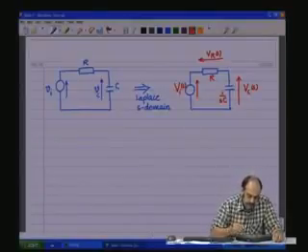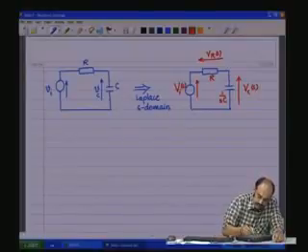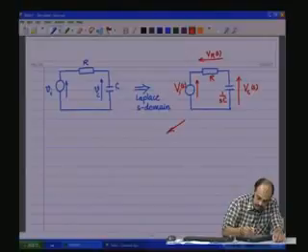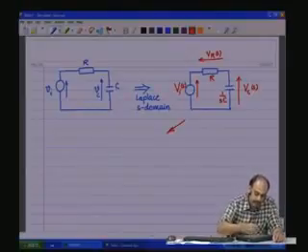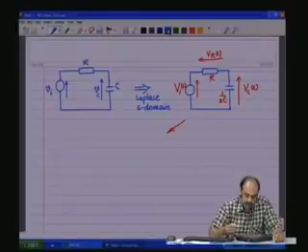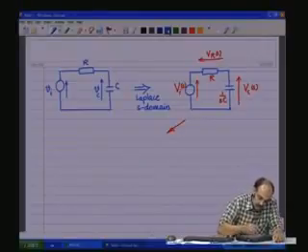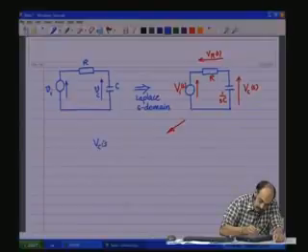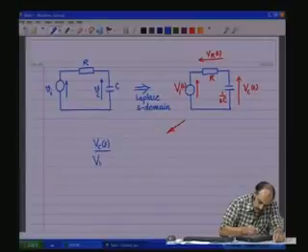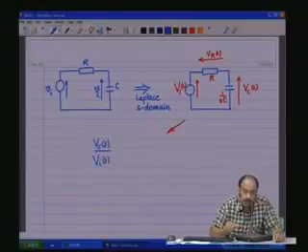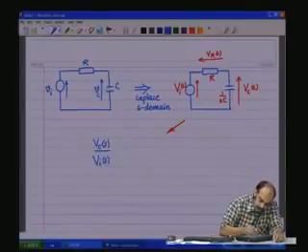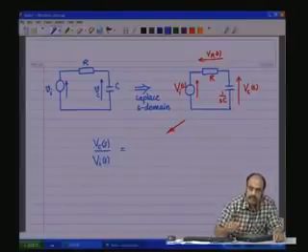So, now this circuit, which we have transformed to the Laplace domain, let us obtain a transfer function. And we have also seen that obtaining the transfer function of the output by the input, Laplace transform of the output by the input as it is defined, is just like in any resistive network.